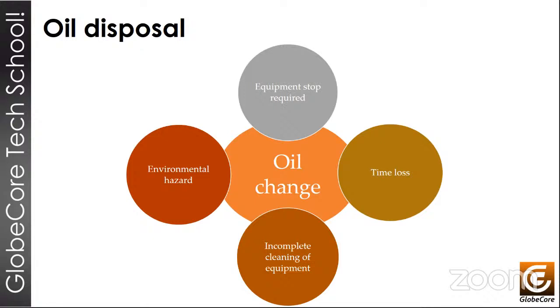This is one thing. Also, of course, there is the downtime, because we need to shut off the transformer when we do this replacement. We need to stop the transformer, then we fill the oil, and then we need to wait for the oil to permeate the paper, and for the level of oil in the transformer to stabilize. All of this takes time. And besides, there is also the cost of the new oil that we have to buy, and the cost of disposing of the old oil. And you know, transformers can contain a lot of oil, so this would be pretty significant.